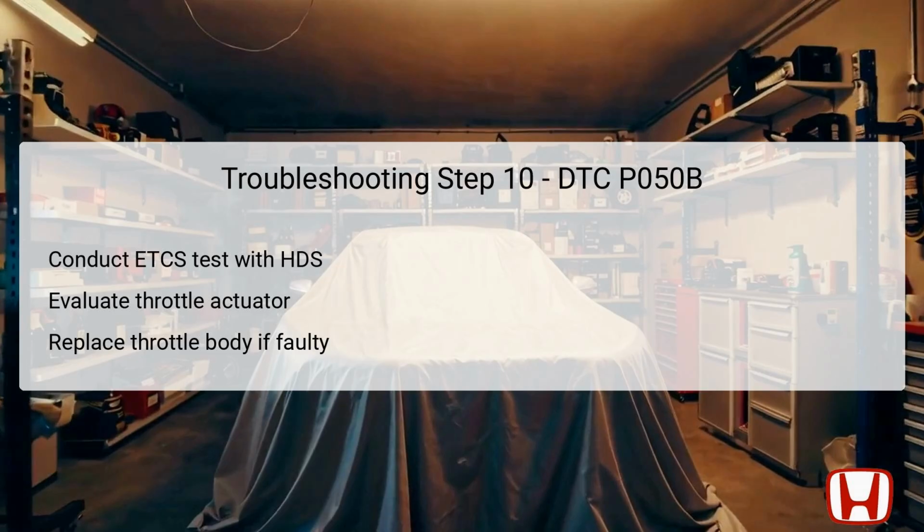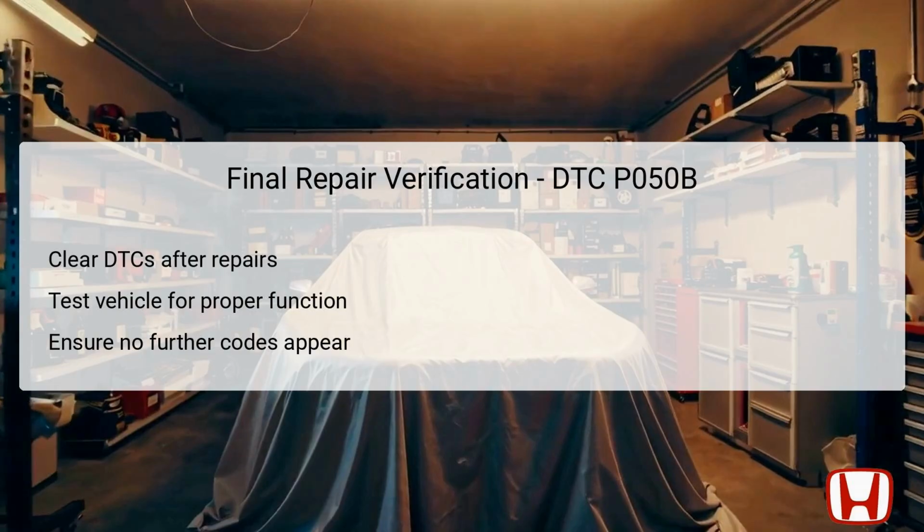If the actuator is found to be functioning normally, you may proceed to the next steps of your troubleshooting. However, if it's revealed to be faulty, it necessitates replacing the entire throttle body to ensure appropriate air management to the engine. Thoroughly conducting this step guarantees that airflow regulation is uncompromised, thus contributing to unbiased analysis of the ignition timing control system.